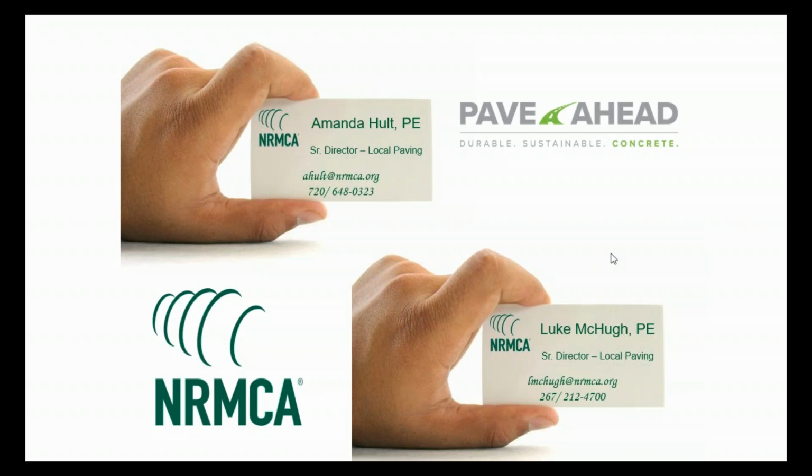When you get to some of the port areas, there are some areas where they will joint. It does help in terms of long-term performance, reducing spalls and things that can happen on natural cracking of RCC. But in some settings, it doesn't make sense to joint just because of the cost of it. So it's not done.